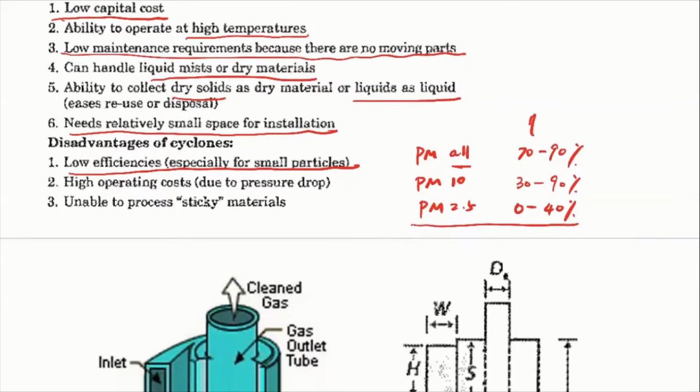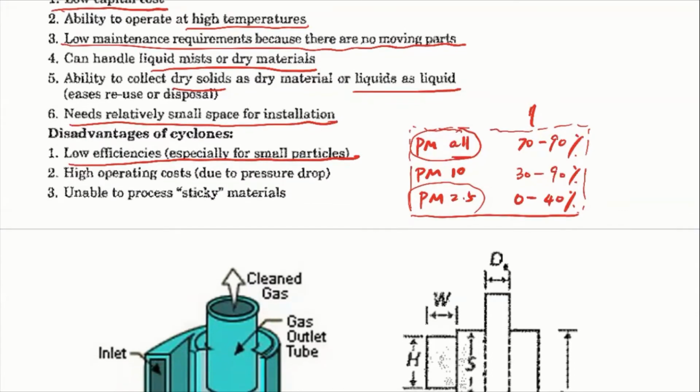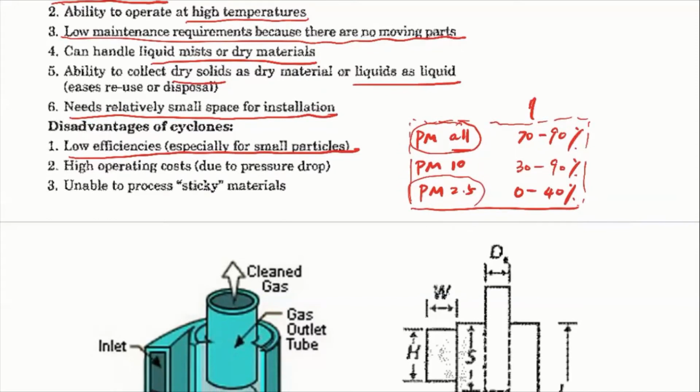Here you can also see how people will show the overall efficiency. A lot of coal-fired power plants, when they talk about their PM removal efficiency, will say that the removal efficiency is 99.9%, but that is the overall efficiency, right? In terms of the very small particles, the efficiency can be very low. And these small particles, because they can suspend in the air for a longer time, can put more health damage to humans. From those words, you can basically understand people try to bring up their highest efficiency, but in the details, it might not look very good.